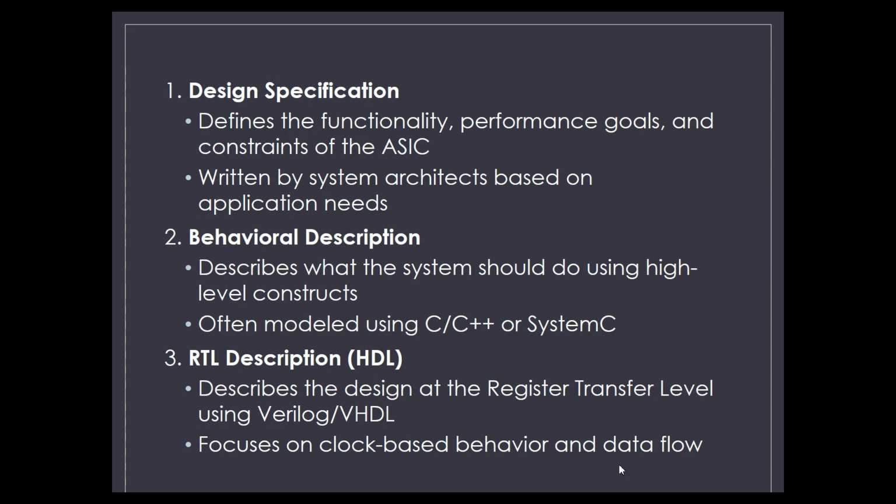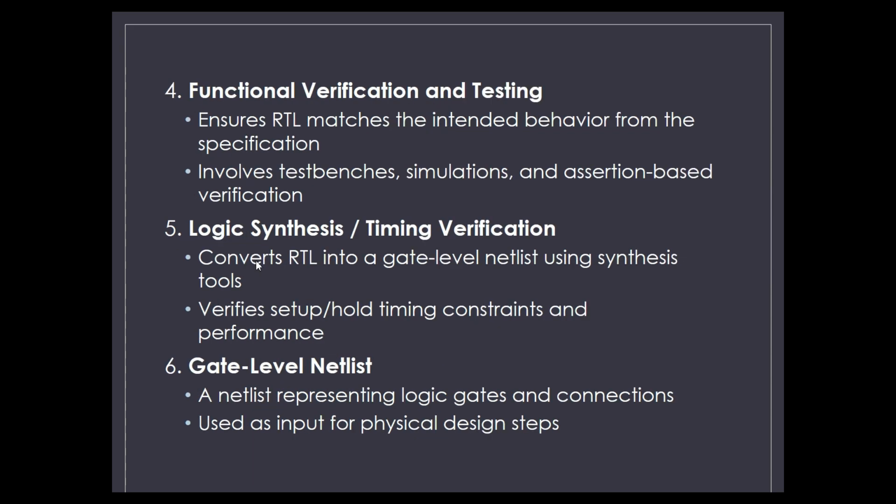Once the functional verification and testing has been completed, we move to the fifth step, that is logic synthesis or timing verification. In this step, the RTL is converted into a gate level netlist using synthesis tools. Here, the concept of setup and hold time also comes in: the design should meet all the setup and hold timing constraints, so as to avoid any setup or hold time violation. The next step after this is the gate level netlist. A netlist representing the whole design in terms of logic gates and connections is developed. This netlist will be used for the further steps of the physical design process.